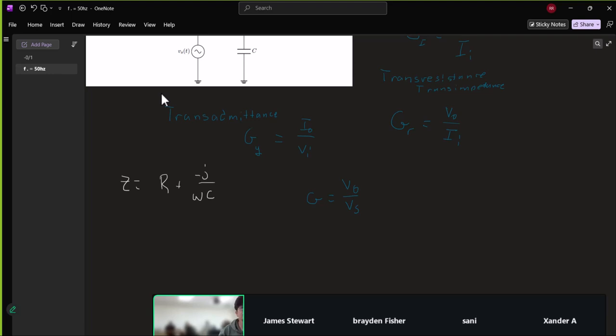So we know by voltage division V out equals V source times ZC over Z total.